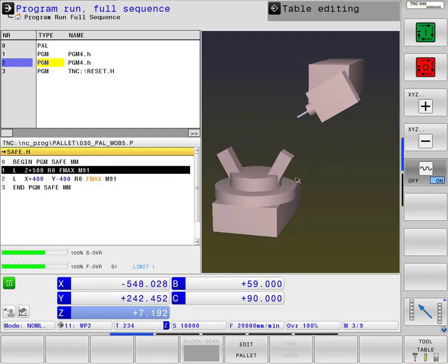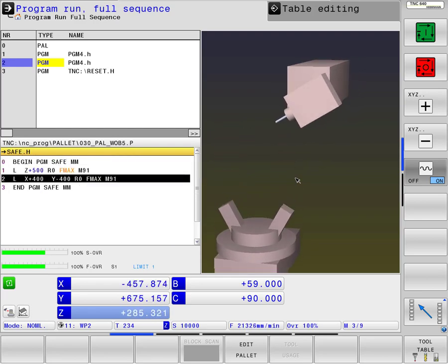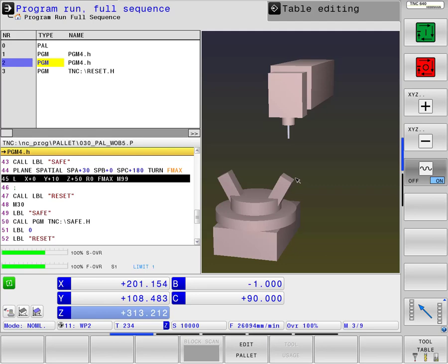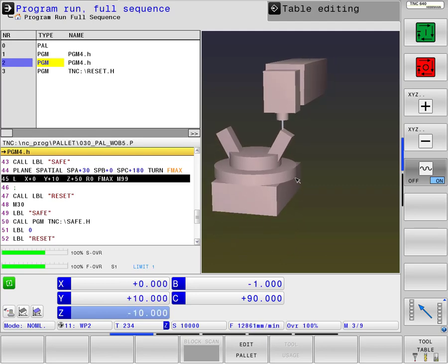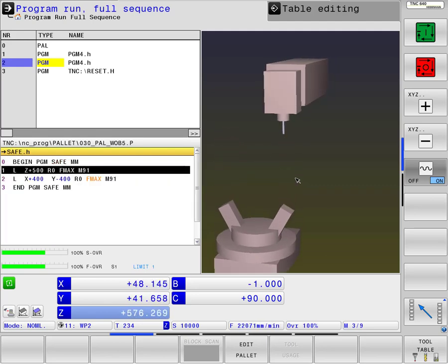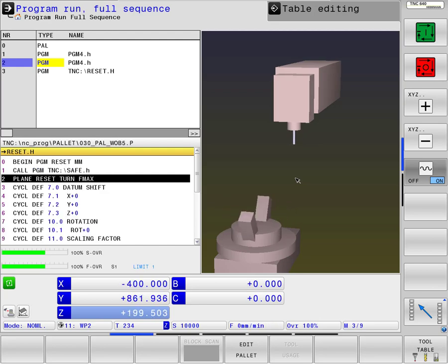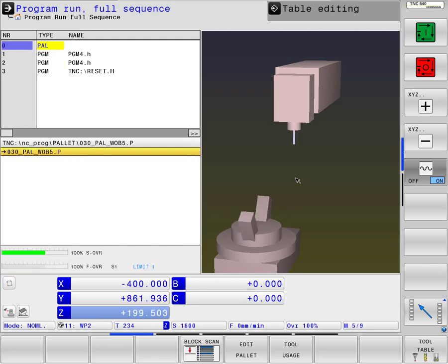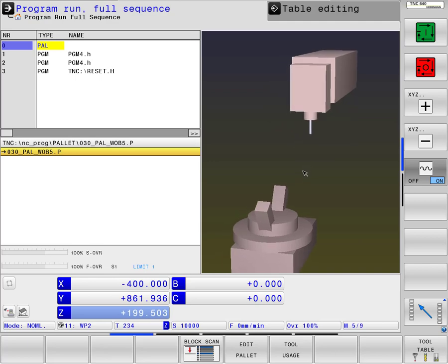So this is a very good opportunity to get more workpieces with a 5-axis machining on the table, because normally we only could do one workpiece on this table, and with a clamping pyramid we can do 3, 4, it depends on the clamping how many workpieces we can do during one machining cycle. And this is a very good opportunity to save machining time.